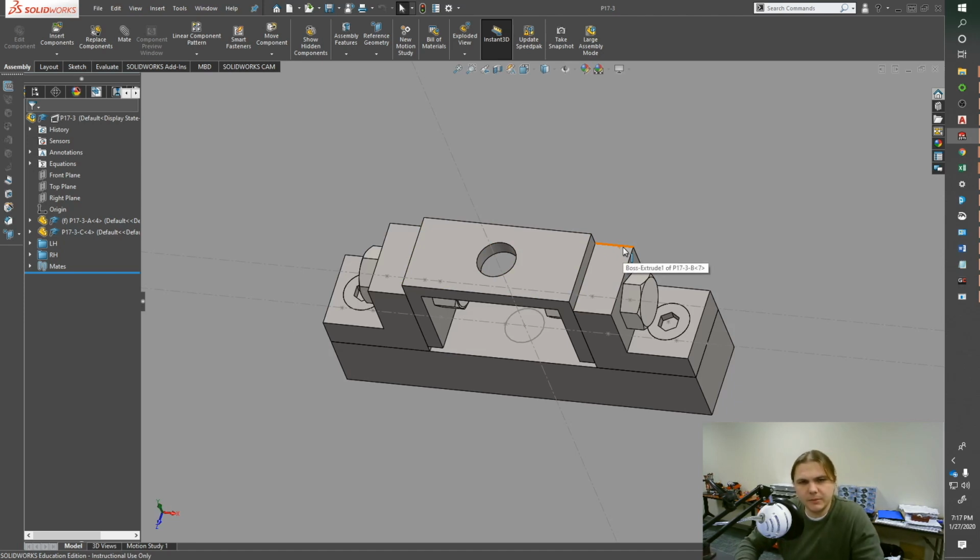So that's what I'll have you do with your roller assembly. I want the overall diameter of the roller and the width of the roller to control both the parts and the assembly. So we can change that one singular text file. The default size was 76, so you should be able to change it to 90, and then the part and assembly will adjust to fit that new diameter size.